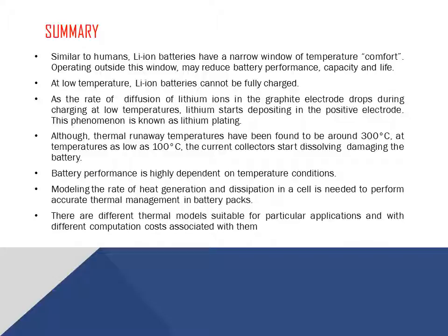Then, we learned that even though thermal runaway temperatures have been found to be around 300 degrees Celsius, at temperatures as low as 100 degrees, the current collectors start dissolving, damaging the battery. We also found out that at temperatures as low as 80 degrees Celsius, the SEI layer starts to break down, causing irreversible damage to the battery.